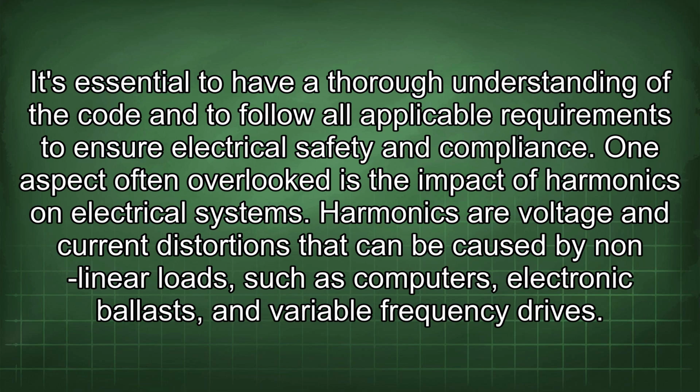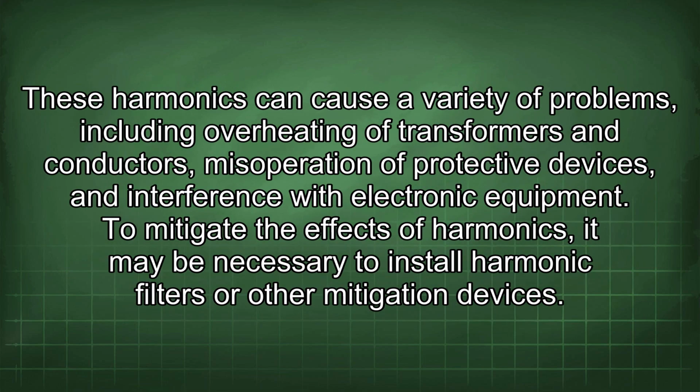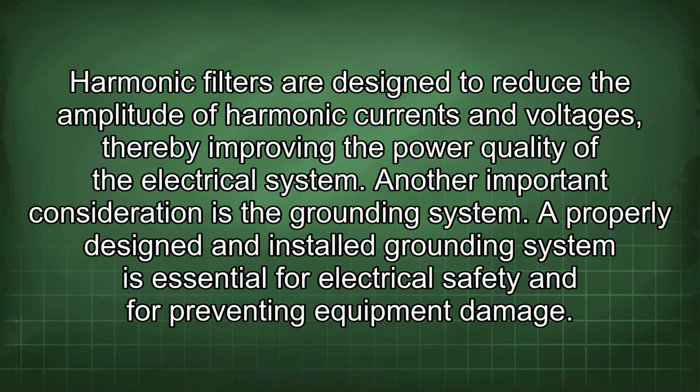Harmonics are voltage and current distortions that can be caused by nonlinear loads such as computers, electronic ballasts, and variable frequency drives. These harmonics can cause a variety of problems, including overheating of transformers and conductors, misoperation of protective devices, and interference with electronic equipment. To mitigate the effects of harmonics, it may be necessary to install harmonic filters or other mitigation devices. Harmonic filters are designed to reduce the amplitude of harmonic currents and voltages, thereby improving the power quality of the electrical system.